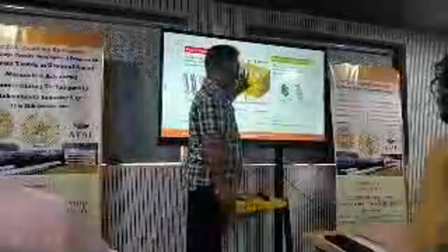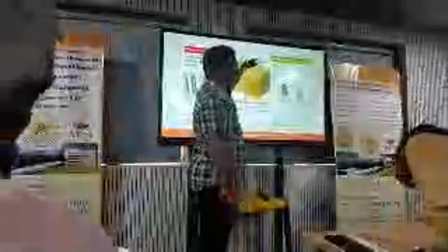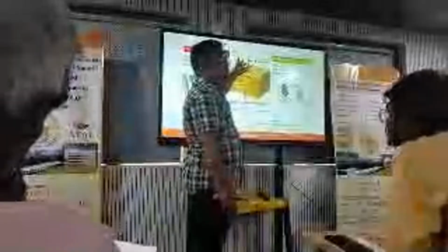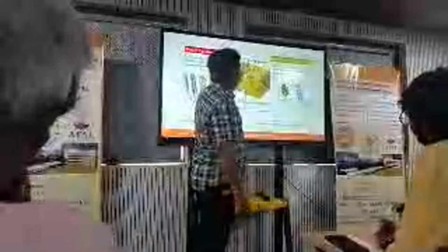Here this is what you can see. These are the batteries, and this is the thermal pack around the battery filled with PCM material, phase changing materials. You will be continuously draining the energy from these batteries. Whenever you start a sports mode or higher usage of battery power, these battery cells will start heating up. This PCM material jacket, this yellow one is the jacket, this blue one are the batteries. That jacket should absorb the heat from the batteries and maintain the proper temperature. If not, the batteries will get overheated and they will explode. Right?